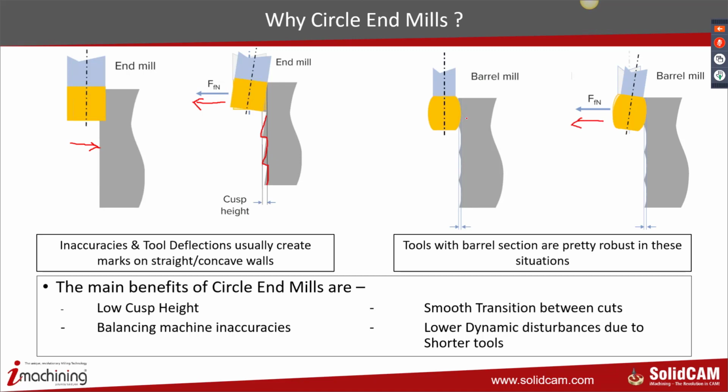But because of this radius out here, the deflections are minimized, or they are balanced out, and the scallop that you started off with in the beginning is maintained all throughout. You get a much better quality of surface, even though you're introducing vibrations into the cut. It's being taken care of by the geometry of the cut.